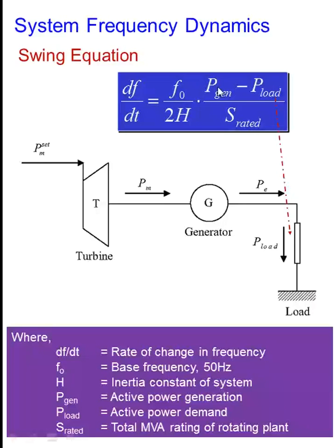Because if I say a step disturbance in the applied load, then at that instant of time, the output power from the generator is constant. So for a step load disturbance, this will result in a deviation, or the amount of disturbance, between the power output from the generator and the load disturbance here, right? Next,